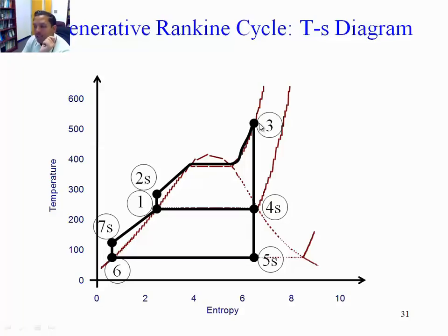That's heat in. Then it's expanded in the turbine, ideally isentropically, to point 4, which might be inside the saturation dome or just outside, but it's vertical, and to point 5, to the intermediate and to the low pressure. And that occurs within the same turbine. And then from point 4 to point 1 is the open feed water heater, as well as